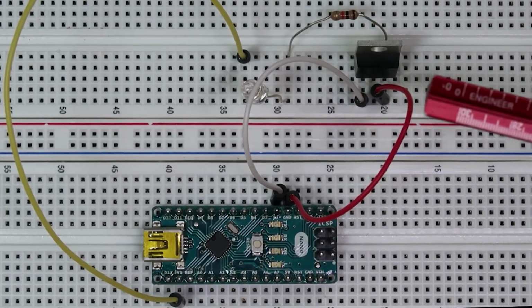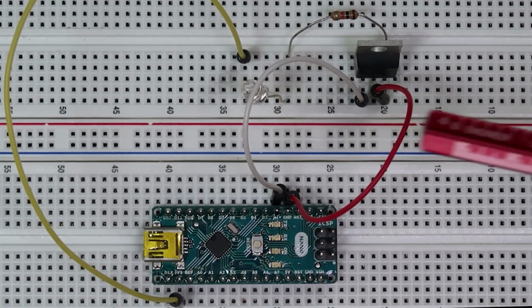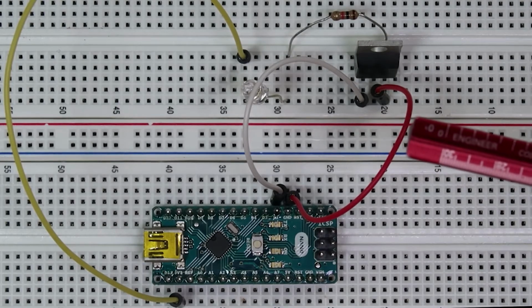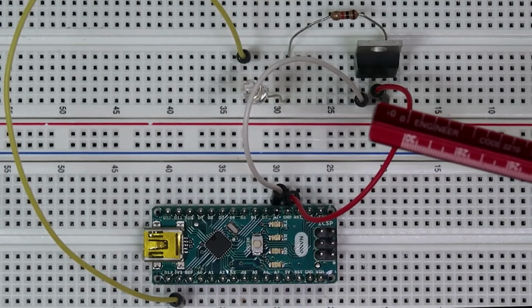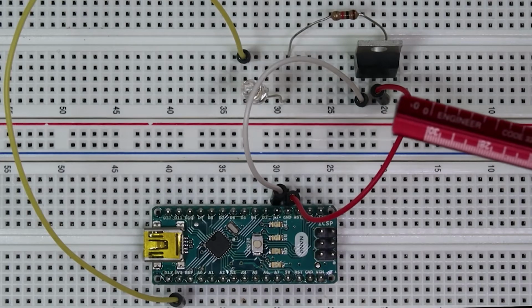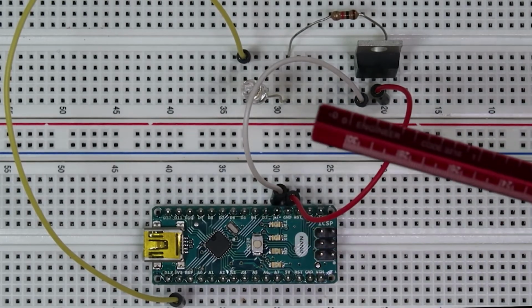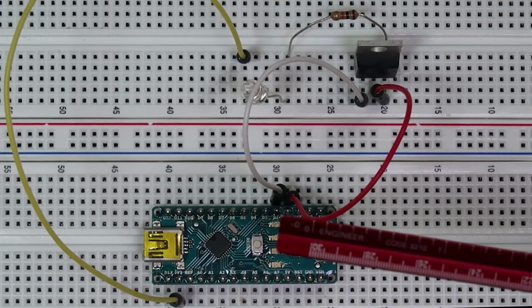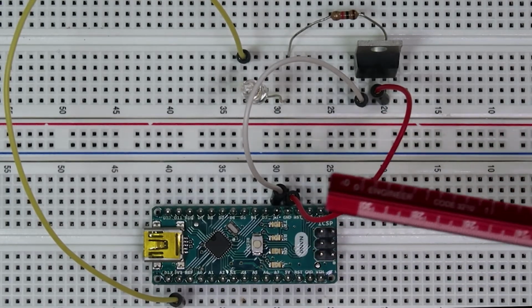The NMOS transistor has 3 pins, one for each terminal. From left to right, they go gate, drain, source. That's why we connected the resistor to the drain terminal, which is the middle pin. Remember that the current flows from drain to source through NMOS. We connected the gate pin to D2 on the Arduino, because we want to be able to turn the transistor on and off from our Arduino. We connected the source to ground.